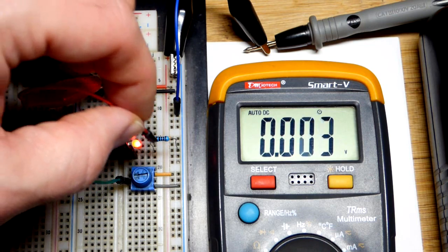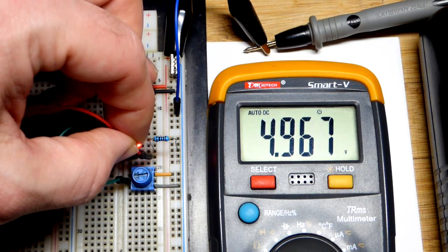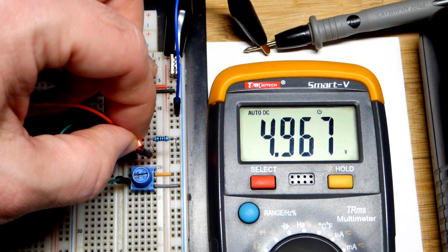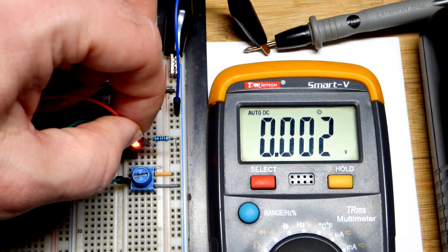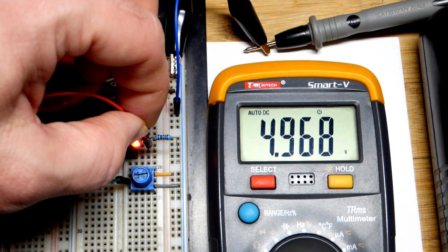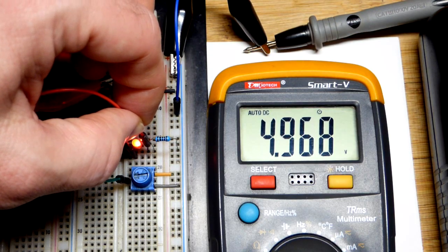That's our non-inverting input, the bottom one. So I can go down there, and it may differ slightly due to resistance, but for the most part, it looks like it's the exact same voltage. So that's going to go across the 1000 ohm resistor as well, right there, the same voltage. So there we can see that. That's the inverting input, though, that's not the output.